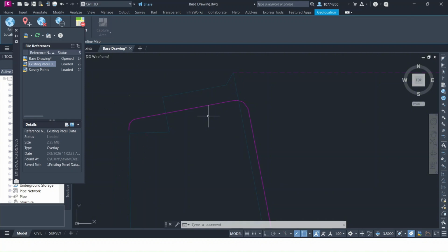So it becomes a problem where you're drawing on the same layer and don't know why this isn't displaying. That's why it's just better to do the X references, because then you can just unload it and bring it back in, and you don't have to be so confused about why it's not working.